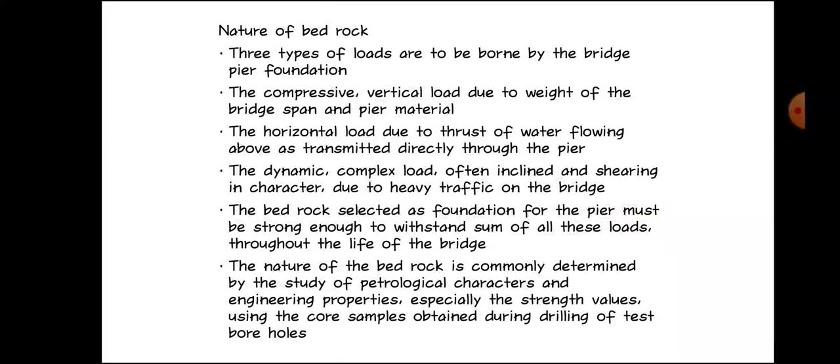Nature of bedrock. Three types of loads are to be borne by the bridge pier foundation. The compressive vertical load due to weight of the bridge span and the pier material. The horizontal load due to thrust of the water flowing above, as transmitted directly through the pier. The dynamic complex load, often inclined and shearing in character, due to heavy traffic on the bridge. The bedrock selected as foundation for the pier must be strong enough to withstand the sum of all these loads throughout the life of the bridge.